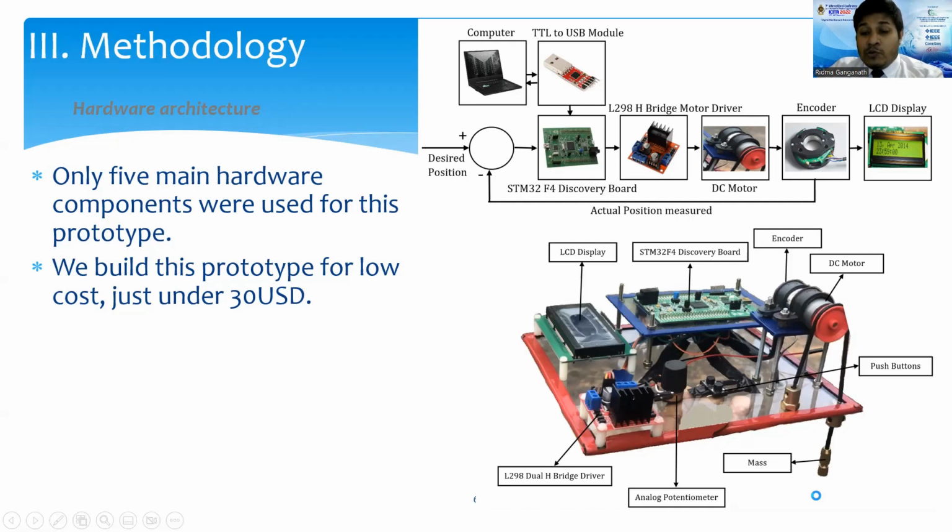An STM32 Discovery board was used to control the position of the armature controlled DC motor by controlling the input voltage of the motor. As this motor control platform was implemented to test control algorithms from basic to complex, a strong mechanical mate is needed to hold the components. Therefore, all the components were attached to a 2.5 millimeter thick perspex board, where the motor was elevated from the board to put on a varying load, and a shield made out of perspex was used to keep the STM32 board tight.